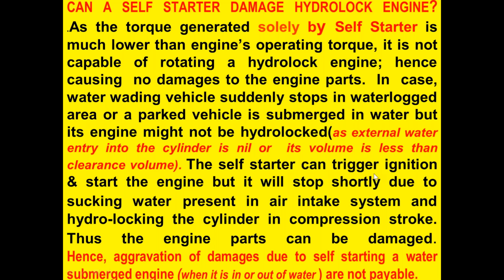The self-starter can trigger ignition and start the engine, but it will stop shortly due to sucking water present in the air intake system parts and hydrolocking the cylinder in the compression stroke. Thus, the engine parts can be damaged. Hence, aggravation of damages due to self-starting a water-submerged engine, when it is inside the water or out of water, is not fair.